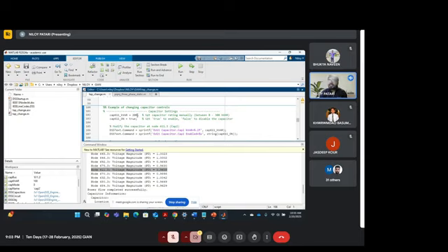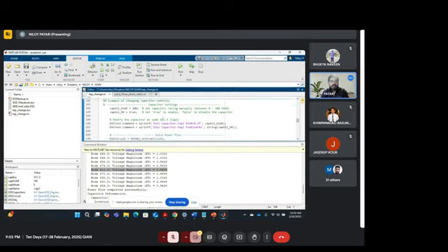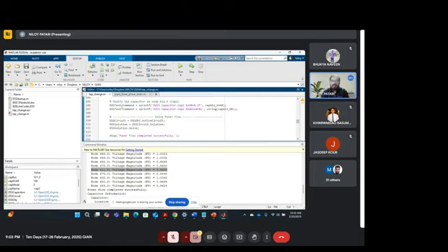Now if I increase this capacitor from 100 kVA to 200 kVA, then it is injecting more reactive power, right? So the voltage should be boosting. So let's just try that. What I'm doing here is setting a new set point, say 200 kVA, and the capacitor on is true, meaning the switch is on, and then I'm putting the DSS text command. So it is editing that capacitor value and the status of the capacitor in OpenDSS.